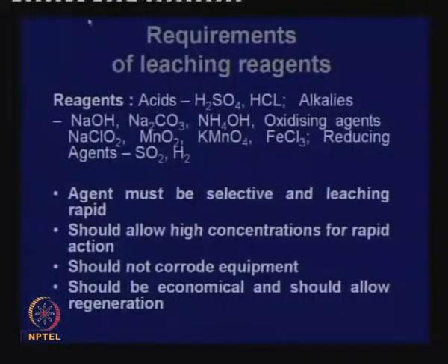So, the whole idea is the agent must be selective, leaching must be rapid, should allow high concentration for rapid action, the leaching reagent should not corrode equipment, it should be economical and should allow regeneration.